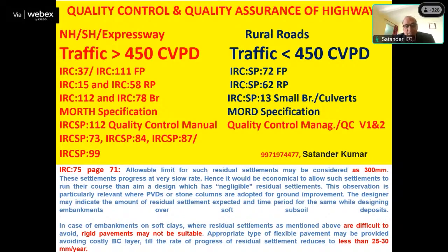On a deck or underpass with flexible pavement, after 6 years it is better to scarify over the deck and underpass also. All over the world, we go for rigid pavement on any road along a river, like the Yamuna Expressway. All petrol pumps, all aprons of airports, the end of the runway, all toll plazas: rigid pavement. Where vehicles stop and start, where oil spillage chances are there, we go for rigid pavement.